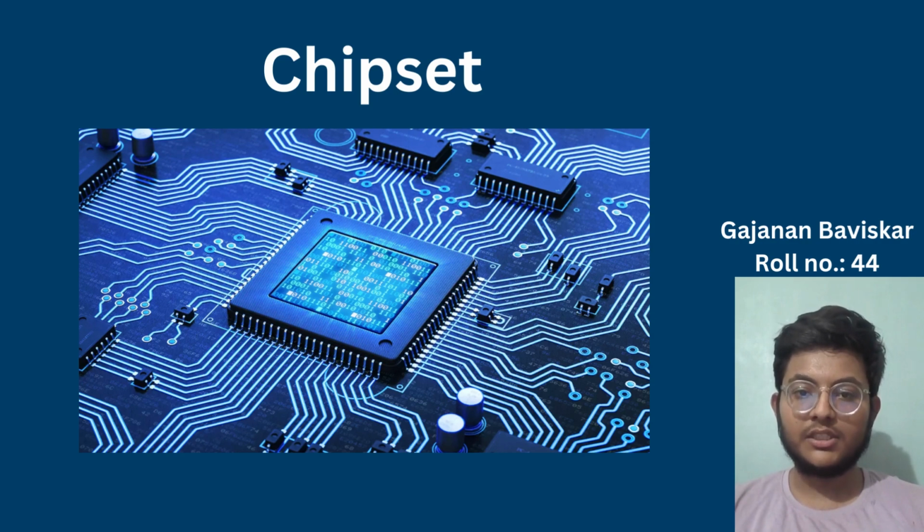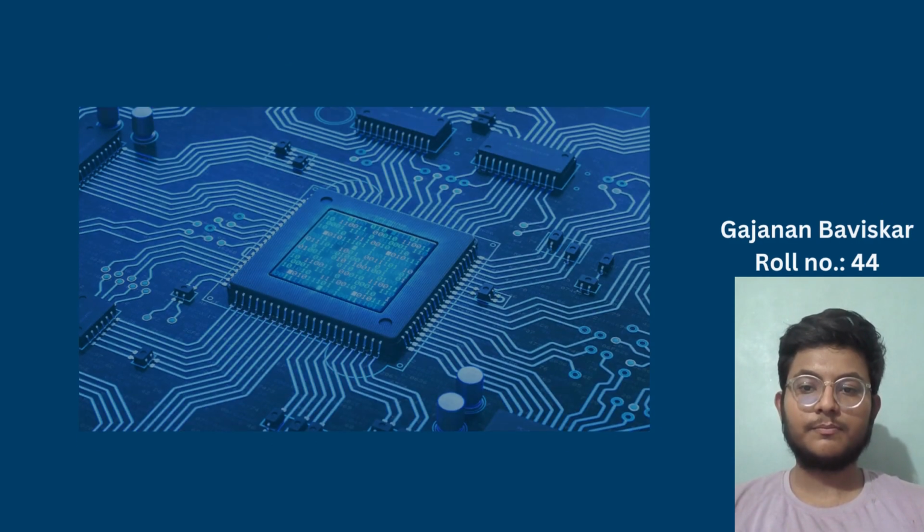New chipset releases may introduce support for faster memory types, increased PCIe lanes, improved power management, updated USB standards, or enhanced connectivity options. In summary, the chipset on a motherboard acts as the central control hub, facilitating communication between various components and peripherals. It consists of the North Bridge and South Bridge components, which handle high speed and low speed connections respectively. Understanding the chipset model and its capabilities is crucial when selecting a motherboard that suits your specific needs, ensuring optimal performance, compatibility, and expandability for your computer system.